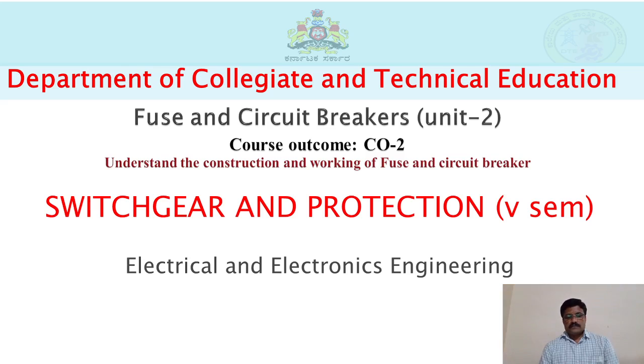After a circuit breaker has interrupted the fault current, its contacts may get burned by arcing, and the oil loses some of its dielectric strength due to carbonization. This reduces the rupturing capacity of the circuit breaker.